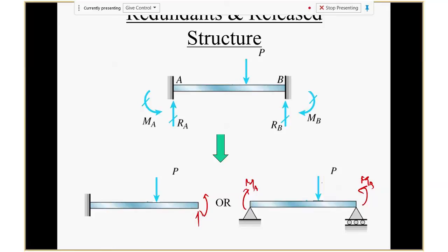Okay. So let's go through the second one first. Basically, how can we use the equation? Let's say for a determinate beam, we can use this equation, or you can use EI v'''' = q, and you can solve the equation and find the answer.